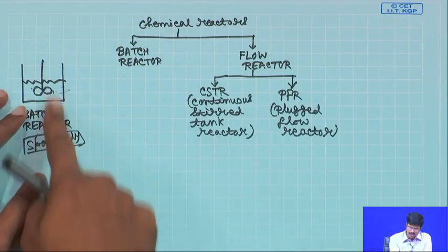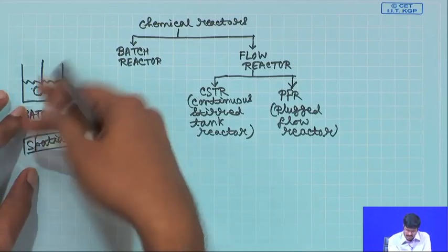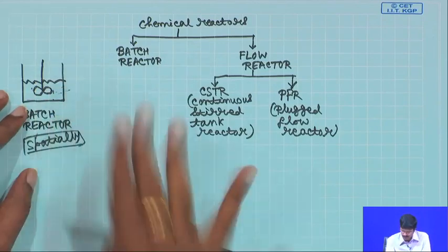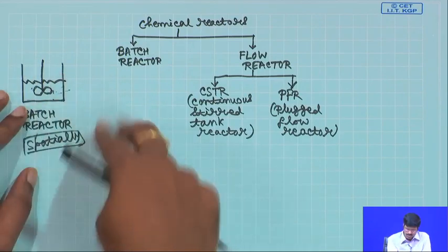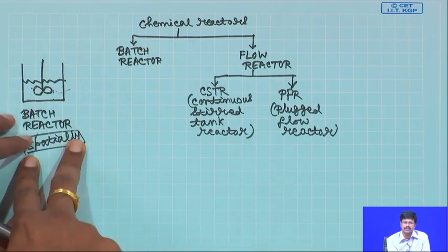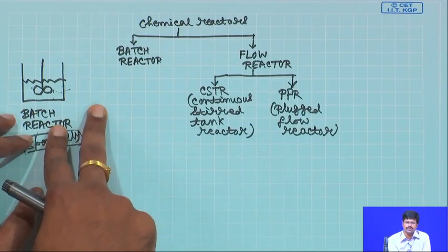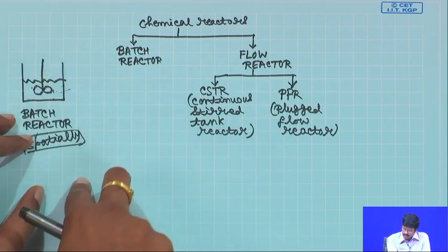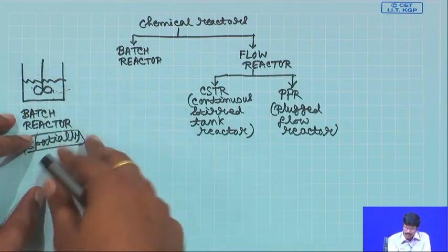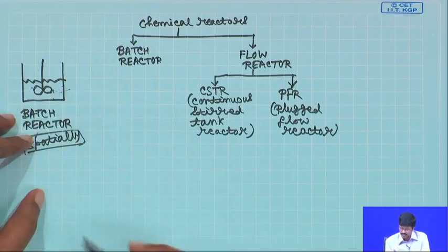So, you can actually put all the components into your system in a batch reactor. This is called the batch reactor in the most simple terms. You charge all the components as feed into your batch reactor, and then you continue the polymerization for a specific length of time, say 6 to 10 hours, and afterwards you take out the reactor mass and then you isolate your polymer maybe by centrifugation, and then you can do various purification processes, and so on and so forth.